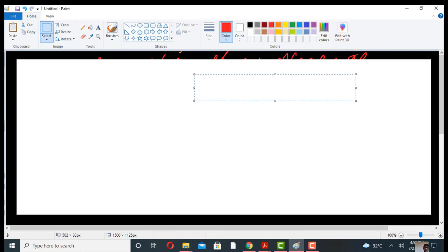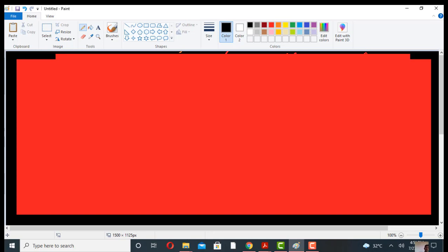We know that during steady state, there is no accumulation of components at the interface. So the flux of component A coming to the interface, NA, is equal to ky, the mass transfer coefficient through the gas phase according to two-film theory, times (yAG minus yAI), the concentration in the bulk of gas minus the concentration at the interface.